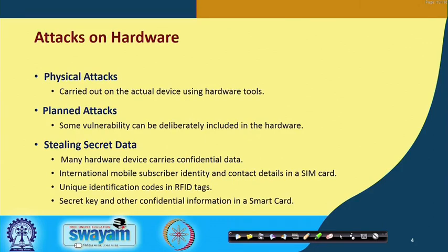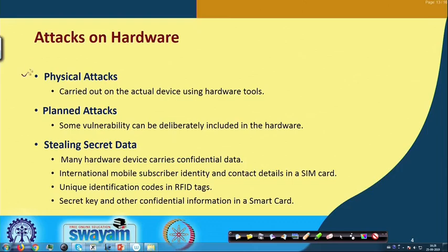Talking about the various attacks on hardware that are possible, let us try to make a categorization. Firstly, let us talk about physical attacks, where we are actually making some kind of intrusive attack on the device. What do we mean by an intrusive attack? Let us say we are breaking open the device, removing the cover or the protective layer on top, something like that. We are making a physical kind of intrusion in the device, a physical attack.